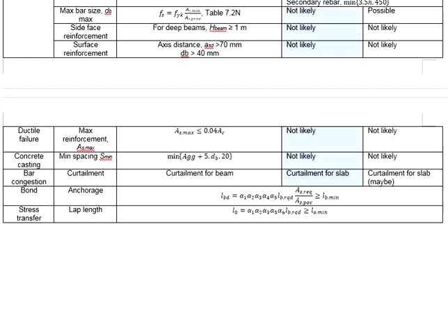Normally, when we arrange the reinforcement bar in the slab and the staircase, we prefer the reinforcement bars to be more widely spaced, as this can reduce the amount of work. For the same required bar area per unit spacing, a larger bar size will lead to greater spacing, as the number of bars required for the same amount of area reduces. This is going to save you time tying the reinforcement bar during construction.